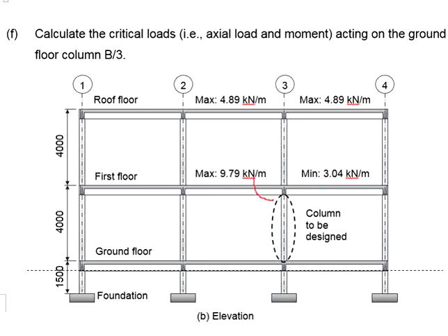This will lead to bending moments in these directions, where the fixed end moments of both beams will counteract each other. Due to the larger UDL here, a larger fixed end moment is expected. You will need to get the balance when both fixed end moments counteract each other.